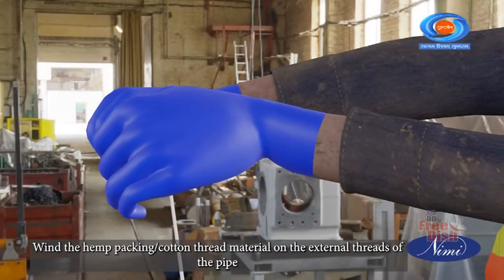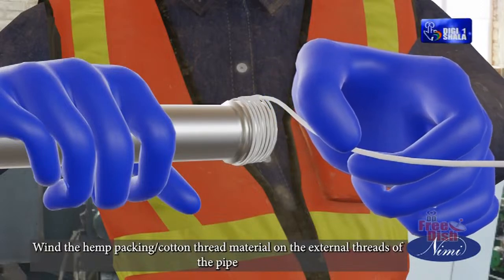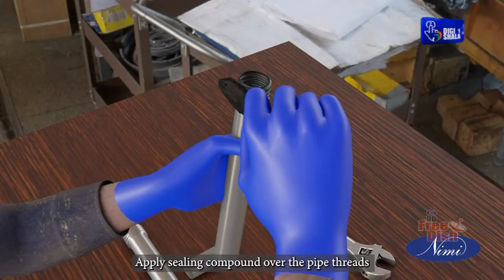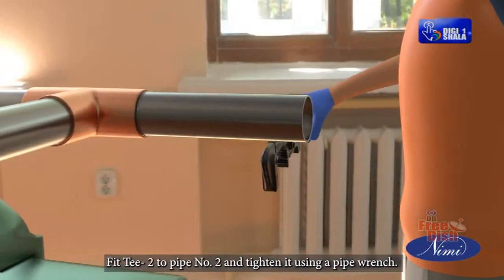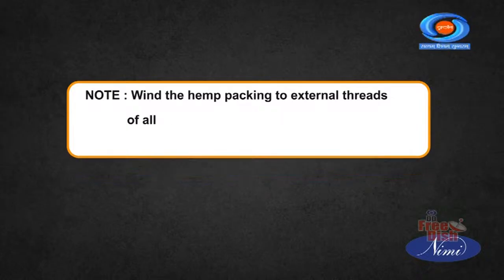Wind the hemp packing or cotton thread material on the external threads of the pipe. Apply sealing compound over the pipe threads. Fit T2 to pipe number 2 and tighten it using a pipe wrench. Note: wind the hemp packing to external threads of all the pipes in standard fittings and apply sealing compound over the threads before joining with the other one.